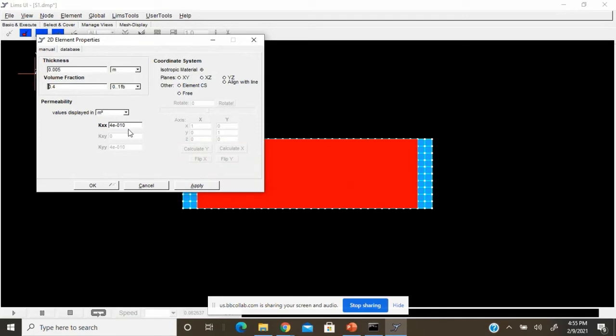So I would ask you to think about another phenomenon when you have an anisotropic layup. How would the fluid flow be? This LIMS software comes in handy here, where you can select your orientation of the fibers based upon your results from this methodology of learning to understand your liquid injection molding.